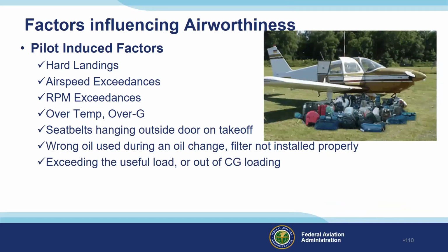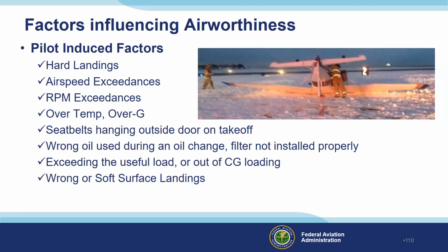Exceeding the useful load or out of CG loading. Do you think all that baggage is going to fit? Looks like my wife packing for a 2-day trip. We've also seen wrong or soft surface landings. Sometimes the flight manual prohibits a landing on a gravel surface, for example. And how often have we seen an aircraft nose over because it's a grass strip and it rained and it's soft and tips over.